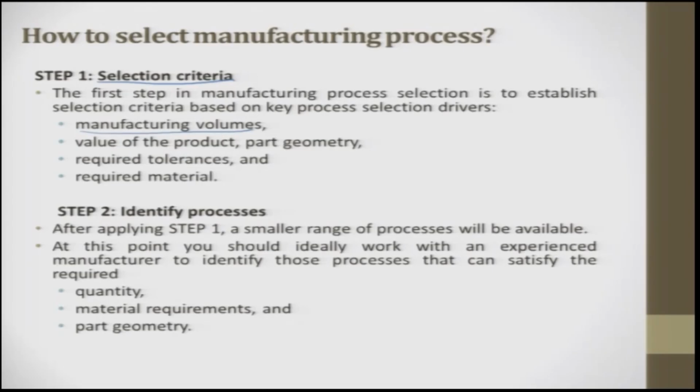So, manufacturing volume is one of the major criteria which helps in deciding a process. Same shaft, same material, only the number changes, the process changes. If I have to machine, I buy a lathe and then I start doing turning, which is not an expensive process. When I start going for rolling, it is a capital intensive machine. So, it is a little expensive.